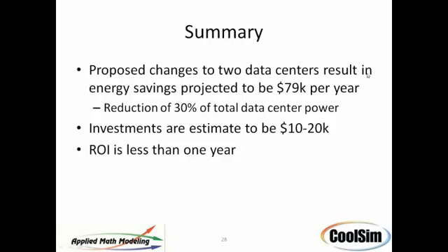And I'm an advocate of variable speed fans. I think it's the right way to get the data center in balance whenever you can use them. And the cost can be modest. For a chilled water-based unit, what they call a CRAH, or chilled water air handler is the acronym, you can retrofit those things for a few thousands a piece. So those can be quite cost effective with respect to changing.